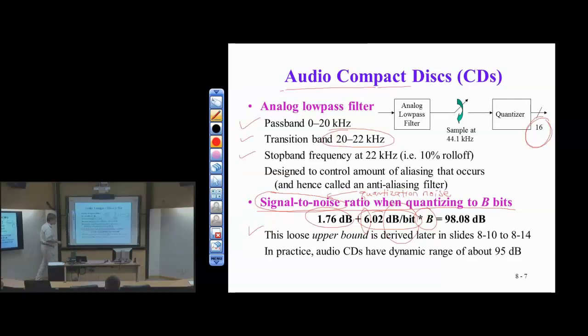Now you can work backwards from this, because this works for any SNR. So if I think about this from pulse amplitude modulation, it turns out the formula is the same. You asked me earlier, where do I measure signal-to-noise ratio? In a communication system, almost anywhere. But in terms of where we do the performance plots, we tend to do it after the equalizer, if there's an equalizer in the system. But we can do it with any SNR to get probability of error versus SNR. If you're on video, you have to move forward to lectures 13 and 14 for pulse amplitude modulation for this background. So you can work backwards with this formula or forwards.